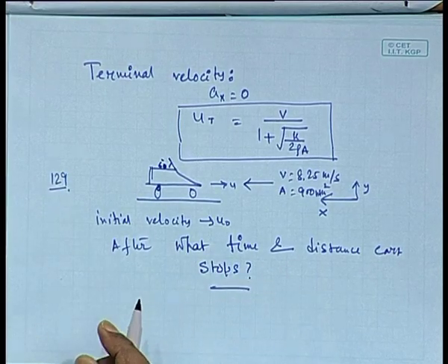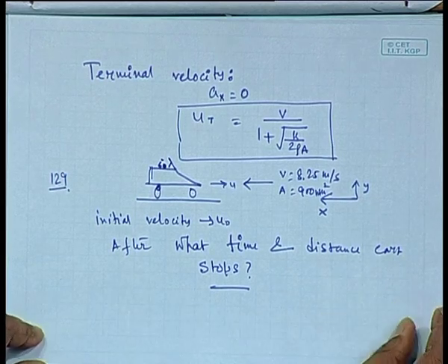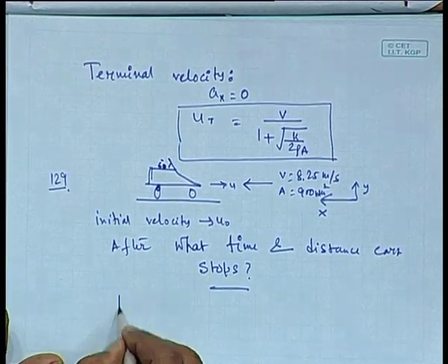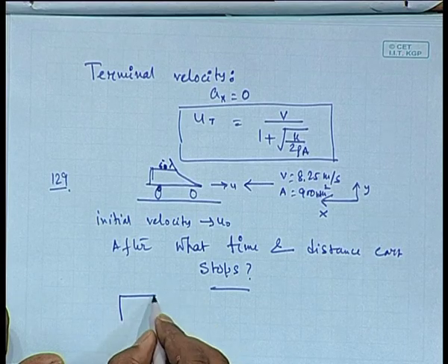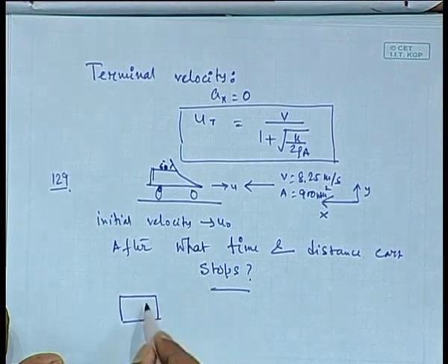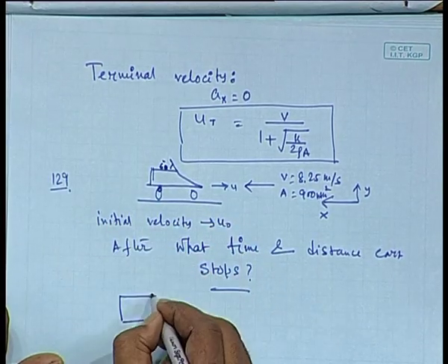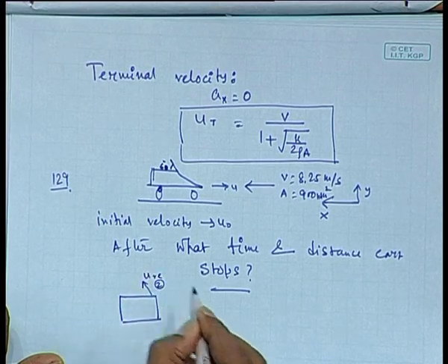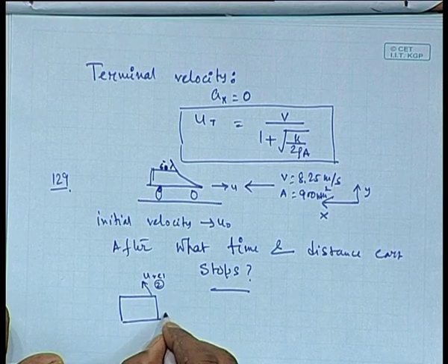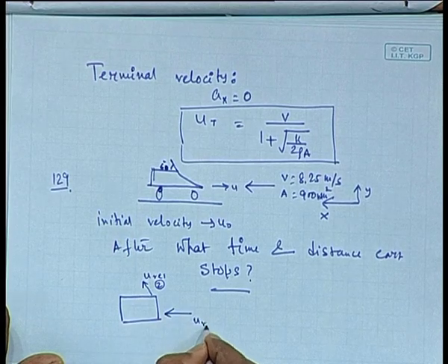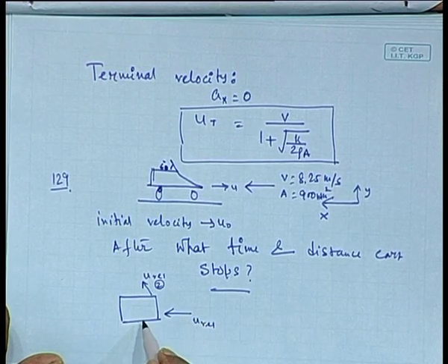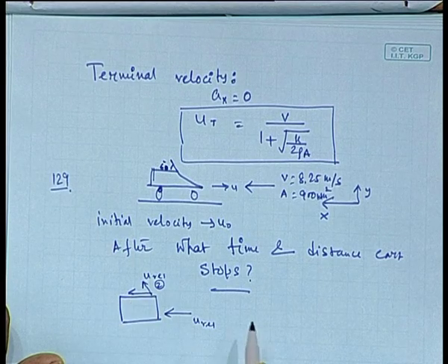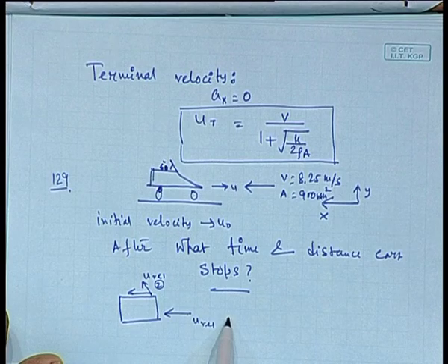Cart stops. Okay. So, again you have to take your control volume including the whole assembly, and the water exit point is point number 2 with u relative. This is in the positive x direction, this is also in the positive x direction. Velocity and normal will be in the opposite sign here, they will be in the same sign there at point number 2.